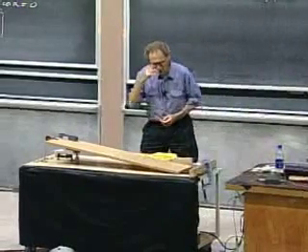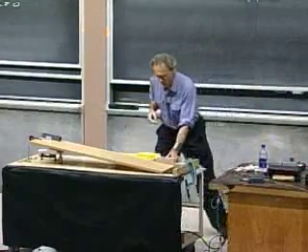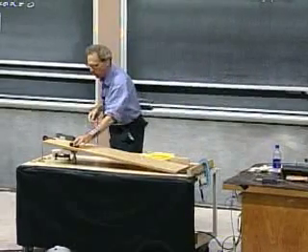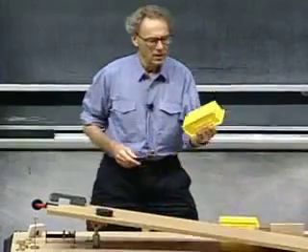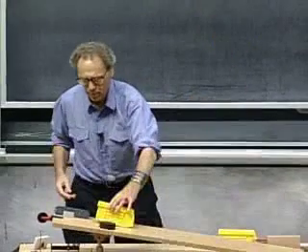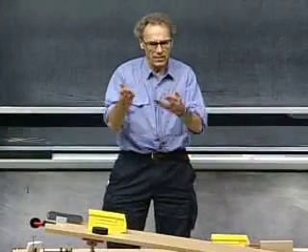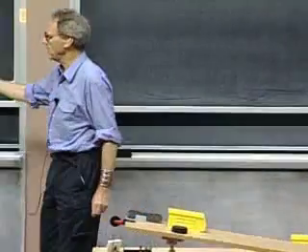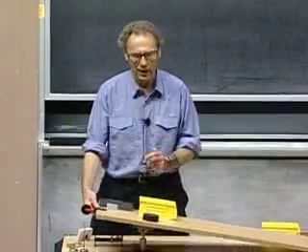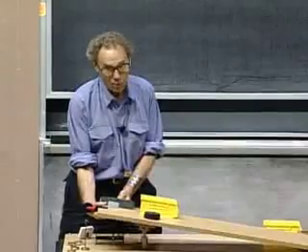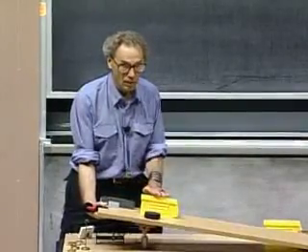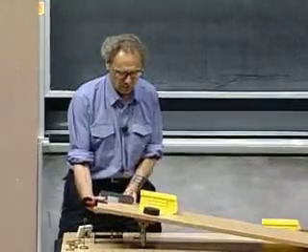The first thing I want to show you is if I take a rubber puck and put it on this incline, and I have a plastic bin, which is quite smooth, it's immediately intuitive that the friction coefficient of this plastic bin will be lower than that of the rubber puck. So when I increase the angle, you expect that first the plastic bin will start to slide and then the rubber puck. If I gave you the angles at which that happened, you could calculate the two values for the friction coefficient, which I will do later. So all I want you to see is that this one will go earlier than that one. So I'm going to increase the tilt.